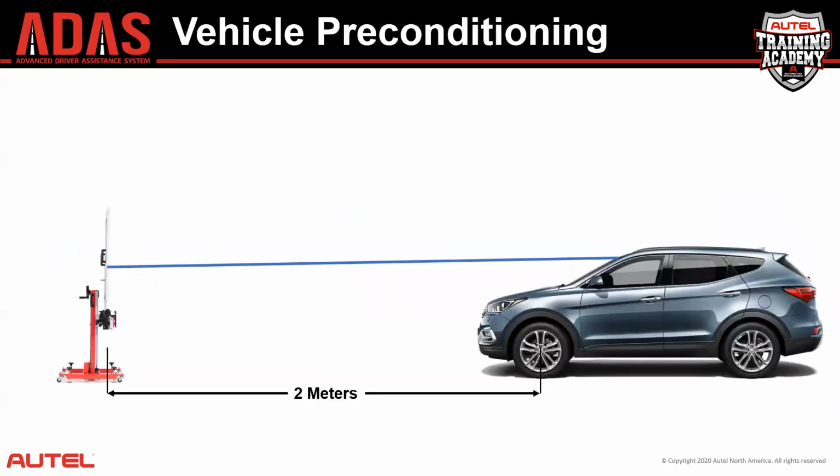so here's that same vehicle being set up for a calibration. The camera is looking at a specific point, and that happens to be the center of our calibration target. The OEM tells us in this case that that target needs to be positioned 2 meters in front of the vehicle, measured from the center of the front wheel, and a target is placed at a specific height, which matches the camera height minus the pitch. So the camera will be aimed precisely at the target.